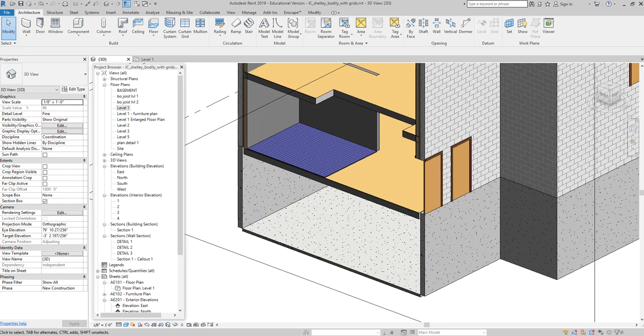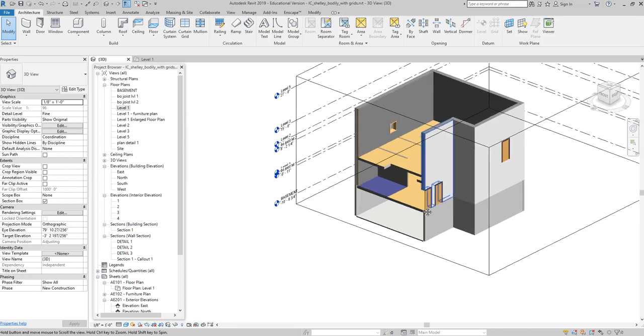They can be tagged, which is really great. And we sketch them, or we create the boundary of them, using the sketch tool, just like we do with a floor, okay? You assign them to a level. However, the levels function just slightly differently than a floor, which we'll talk about as well, okay?